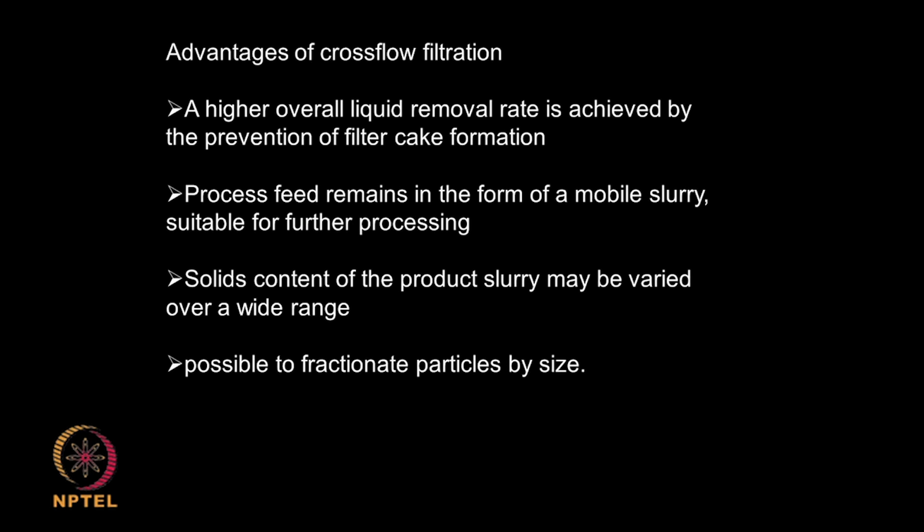Okay. So, what are the advantages of cross flow? A good liquid removal rate is achieved, because you are not allowing it to form large thick cakes, and in a dead end thick cakes make the liquid flow less and less, and after some time the liquid flow can totally stop. And the feed always keeps moving on top. So, we can take it and do further processing, unlike a thick and dry cake, where we cannot do further processing unless you put it again in a slurry.